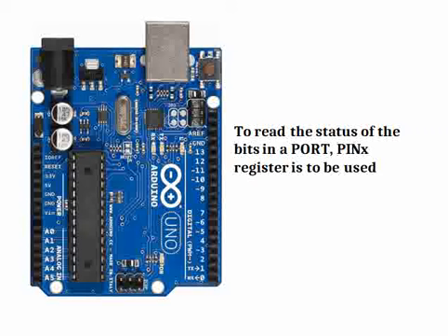Next thing is, in between the program, you might want to read the status of the port. For example, let us assume in port B, we have set 2 pins to high and the other pins are low. At some point in the program, you might want to know which bits are set and which bits are unset, that means which pins are enabled as high and which are low.